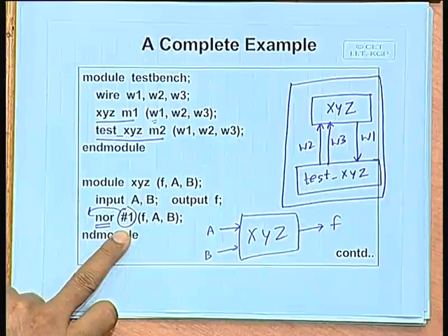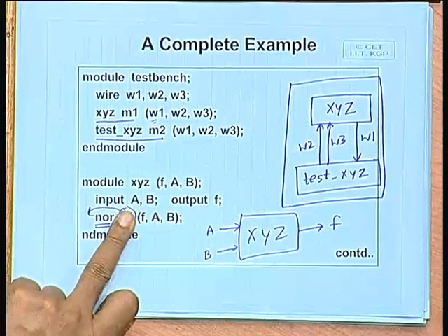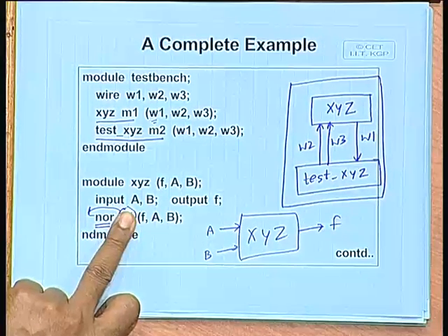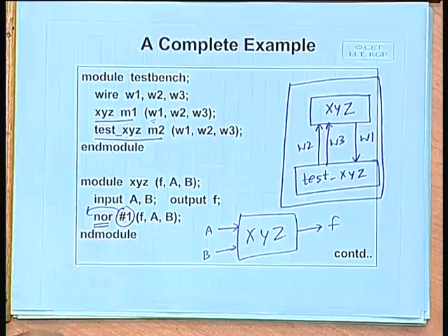And then module X5, where you are given one delay #1 before NOR. That is not synthesizable. This is not synthesizable because the synthesis tool will be ignoring this. Yes, you are true.